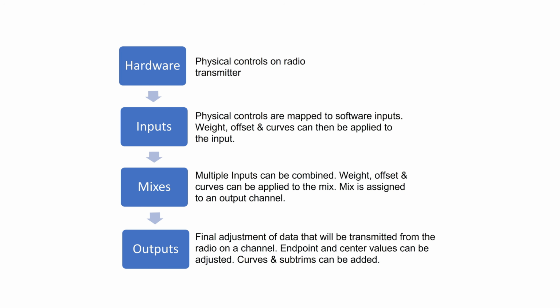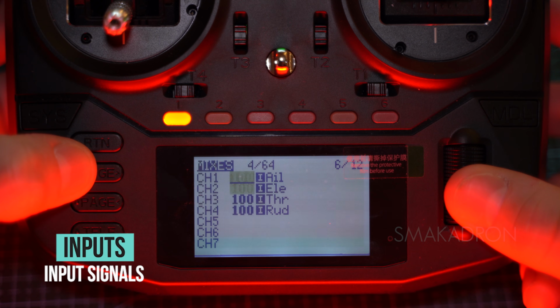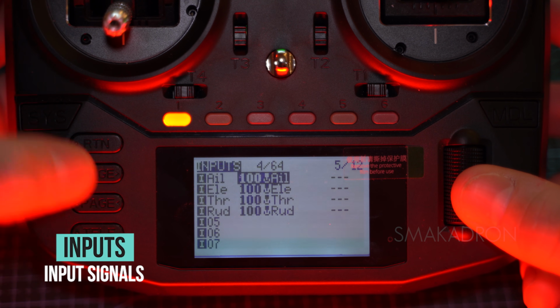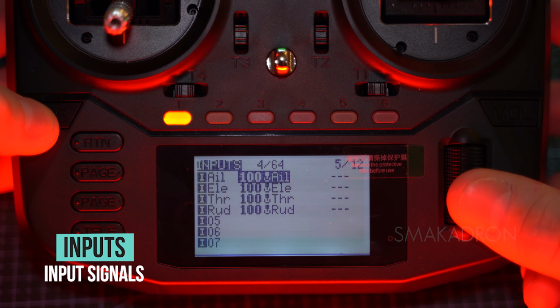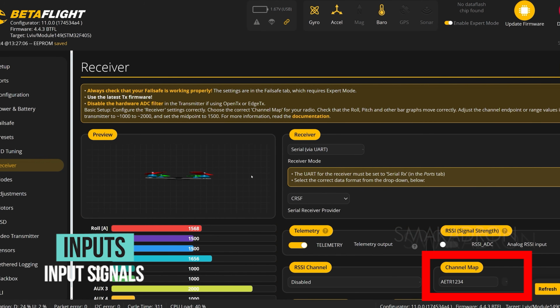Some pilots believe that configuring inputs is not a necessary step, as they can directly configure all the necessary parameters on the Mixes tab. This can simplify and speed up the setup process. In many cases, EdgeTX automatically assigns the main physical control elements, the joysticks, to the main channels: aileron roll, elevator pitch, throttle, rudder yaw. This is why in the Betaflight software you see TR1234 or ETR1234. The numbers represent the number of primary control channels, followed by arm-disarm and flight mode.